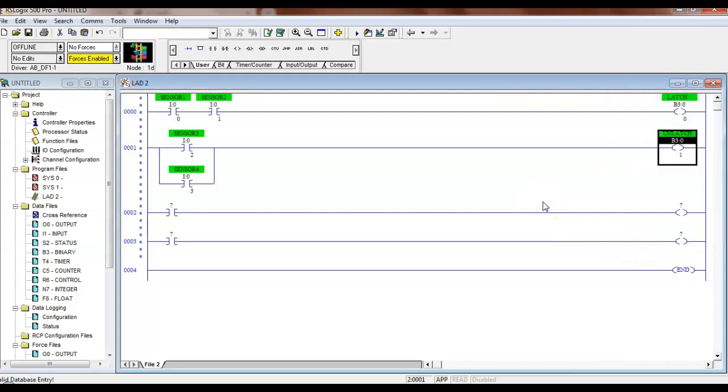To explain this, the one question would be, why are we using B rather than just a simple output? Because I would just sacrifice my output when I'm not going to use this coil, this simulated coil, to turn on a light. I'm not using this to turn on a relay. All the contacts controlled by that coil are going to be inside my program.